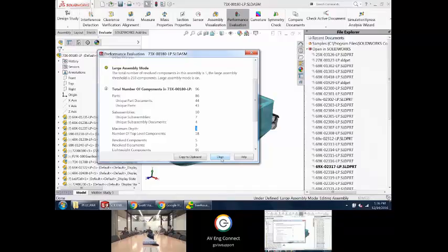If I added another sub-assembly inside of that, you go to 4 levels deep, 5 levels deep, and so on. It's a good idea to not go above 5 levels deep as far as your maximum depth. It gets difficult for the bill of materials functions inside of SolidWorks to get all the parts correct if you go too many levels deep, depending on how you have your bill set.